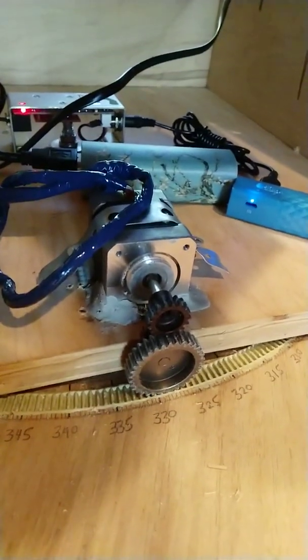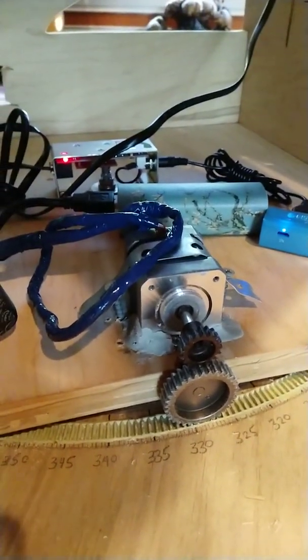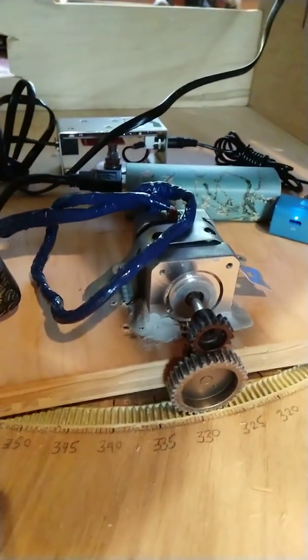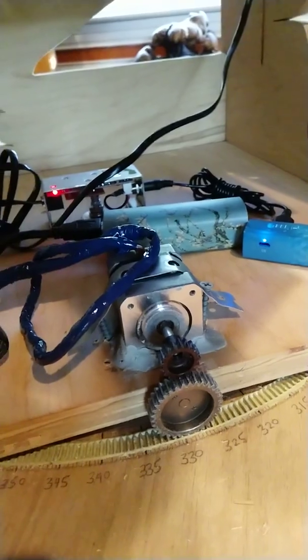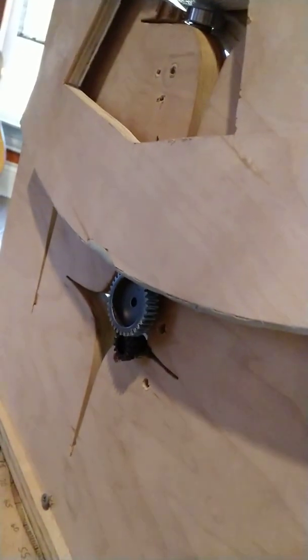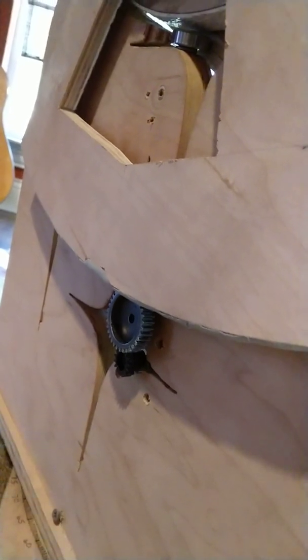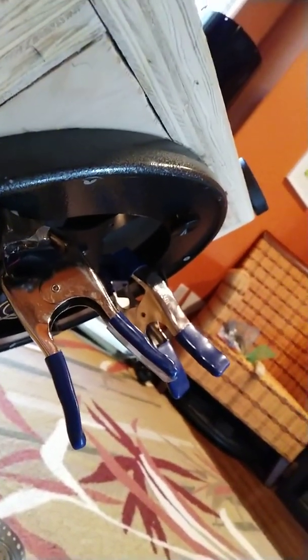For the base, the amount of torque doesn't matter. I used the roller bearings from the original Zhumell Z12 base to greatly reduce the friction instead of using the Teflon pads. So the base can spin around all day. It doesn't really need much torque. But this one was having a little bit of a problem once I put my eyepiece in, being able to lift it back up. So I added some counterweights. That's what that counterweight up there and the 2 clamps were, to add enough counterweight to counteract that huge eyepiece up there, and now it's able to go up and down.